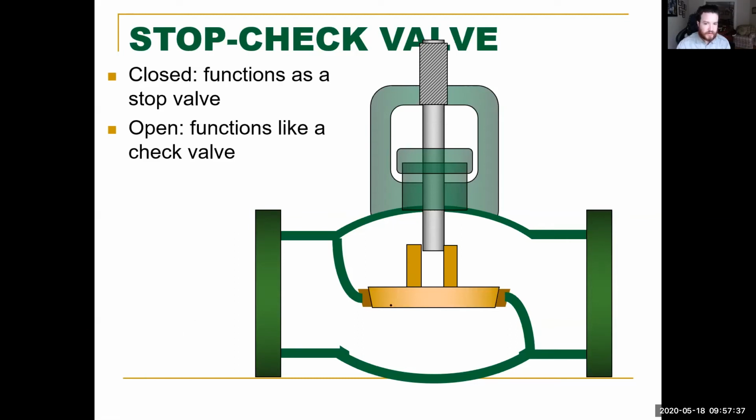So when it's in this position, what's great about these things is you can use them as throttle valves. But you can use them as throttle valves only when there's pressure. So say you're operating a fuel pump, and you turn on your fuel pump and it's sending fuel to whatever tank you want it to go, and this valve is open.